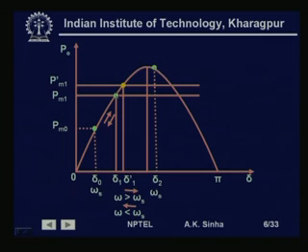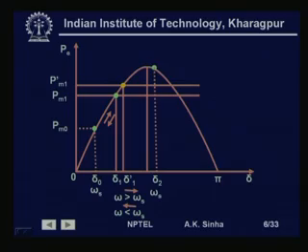So, this is the kind of dynamics that takes place when we have sudden changes in the mechanical input or electrical output from a turbine generating system connected to an infinite bus bar. We will get a sustained oscillation between these 2 points if there is no damping.